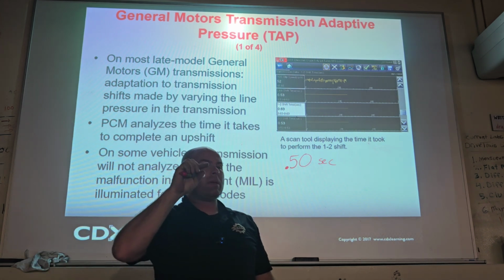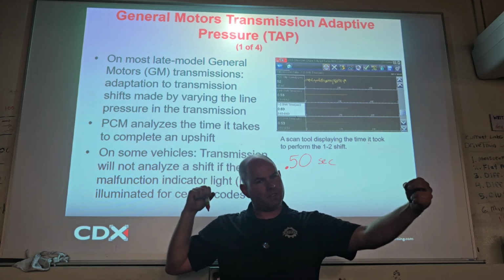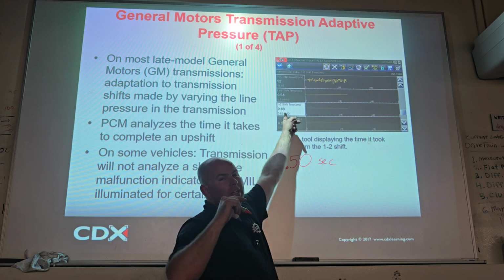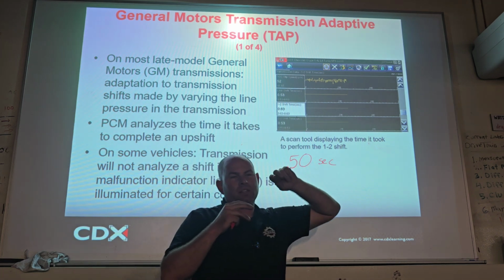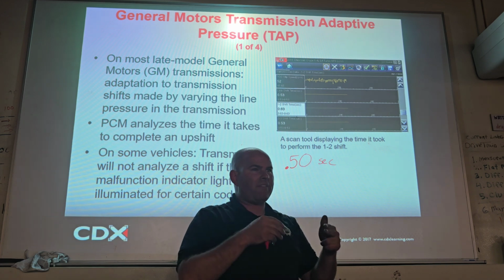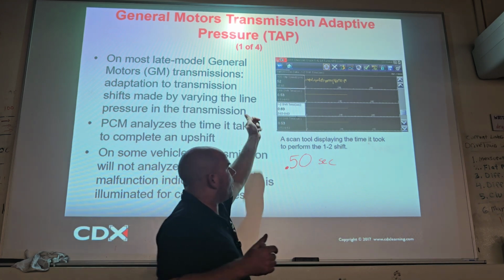It's not about the timing, it's how long it took. So this is when first lets go and second comes in. We want it to take a half a second, but it took 0.63. That's too long, right? It should drop first and pick up second in a half a second, and now it's taking too long. So what could we do to bring that down?